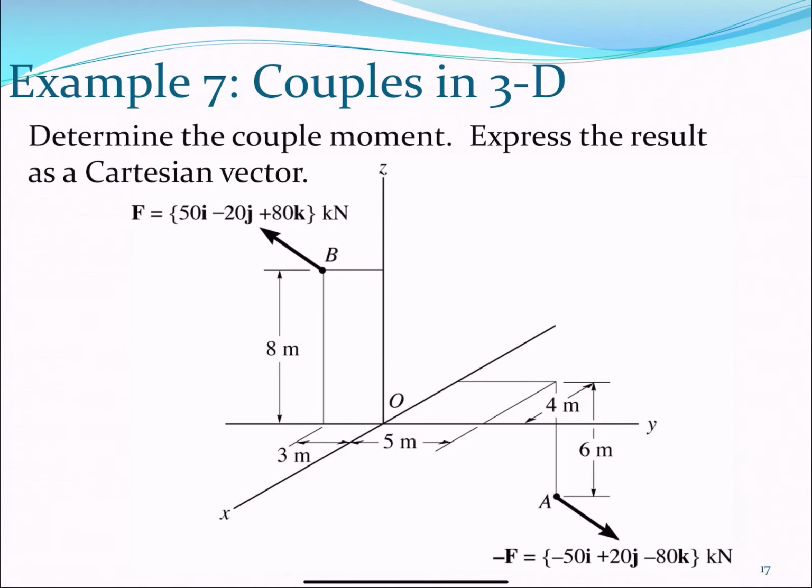And the time has come in which we have a three-dimensional case. You were waiting for this, right? So remember what we discussed, right? We don't have to calculate the moments of these two forces about the origin or about any point in the 3D plane, right? We can just shoot a position vector from force vector to force vector and then cross it with the vector you shot, right?